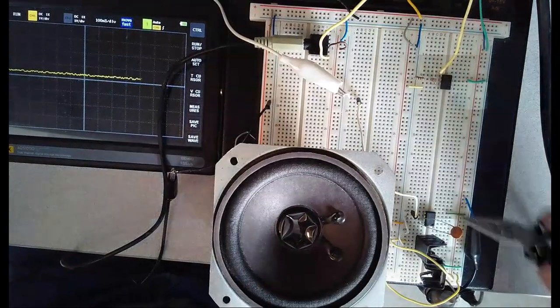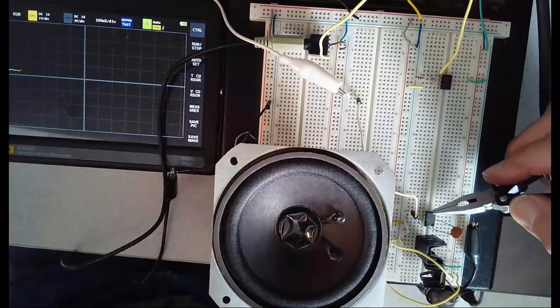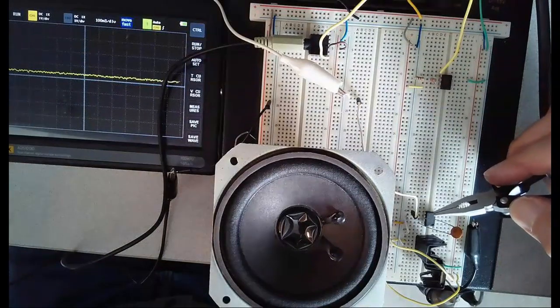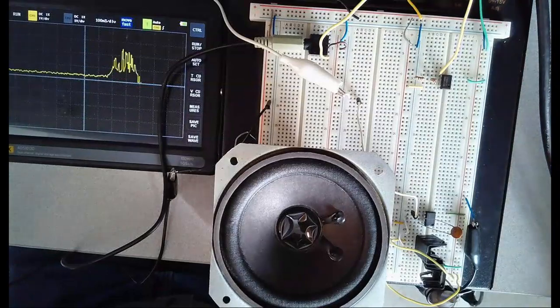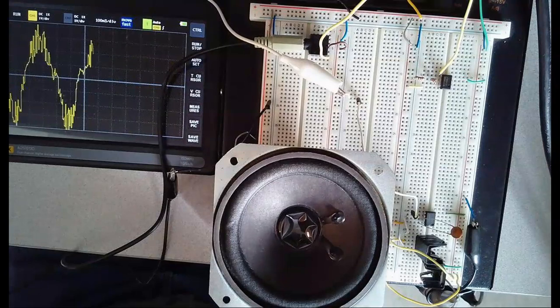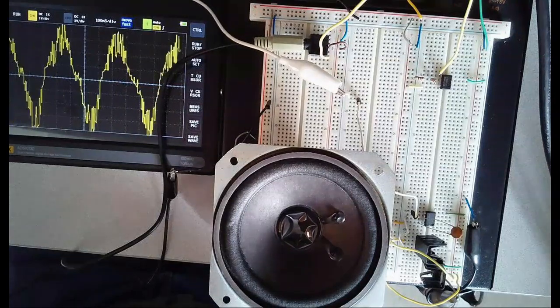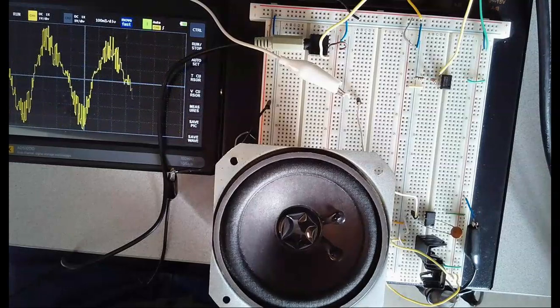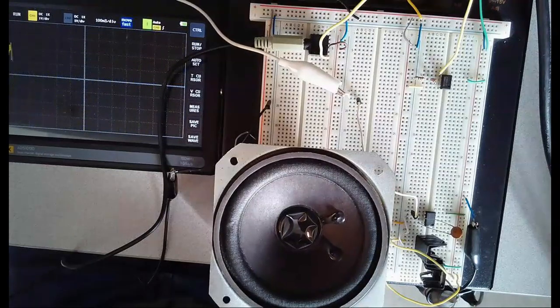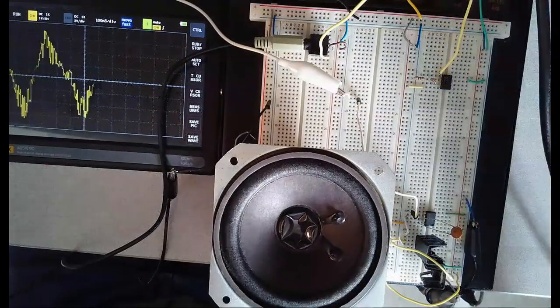Next, here I had the op amp in the front set up as a voltage follower. Instead of having the V minus going to V out, I'm going to take V minus and have it go to the speaker, to the emitter. What that does is that eliminates the crossover distortion. And I got some noise on the signal. This is for a low frequency sine wave, and you can see the speaker going back and forth. Fairly smooth without the crossover distortion.